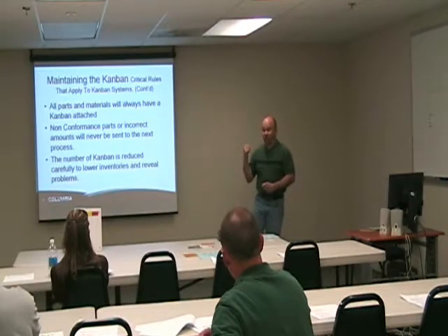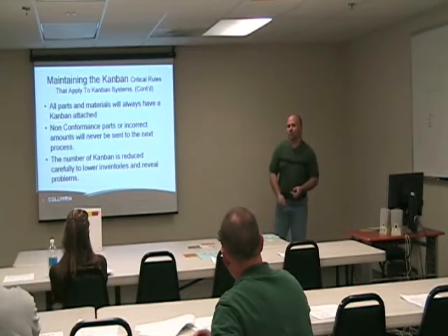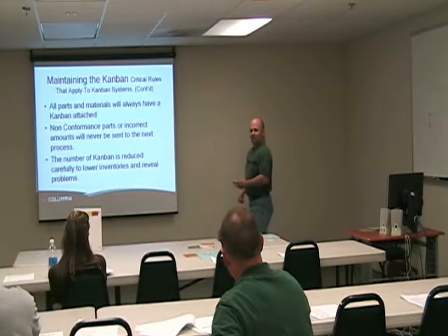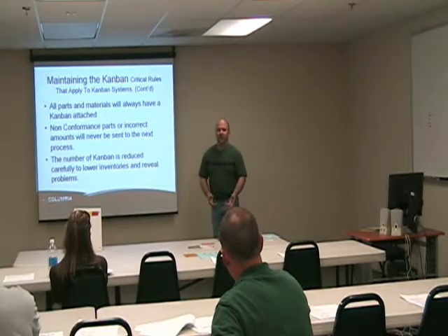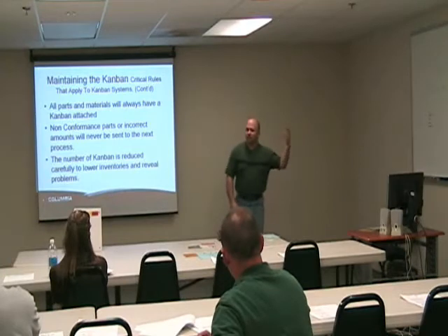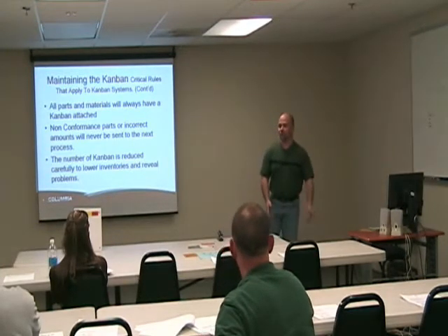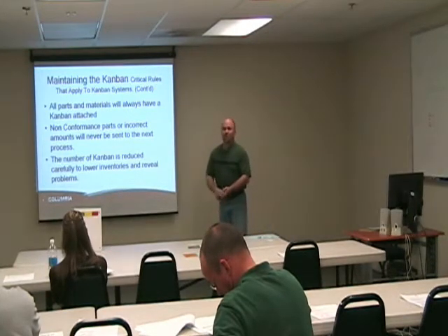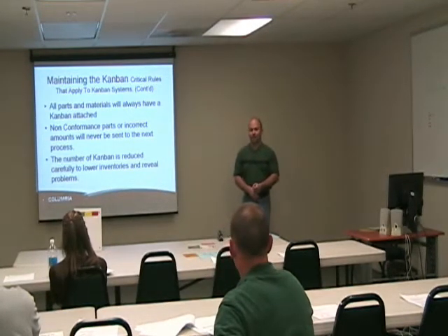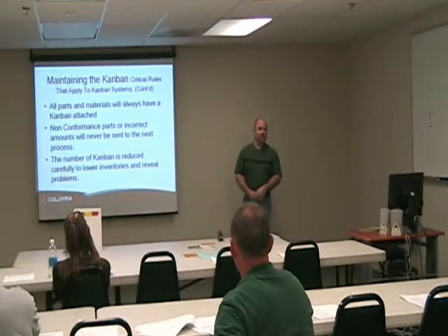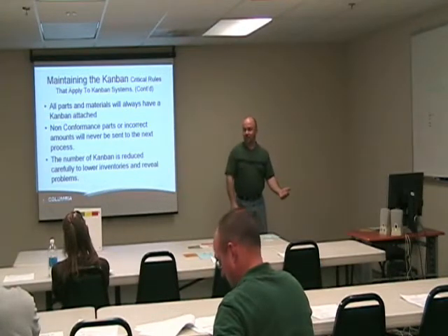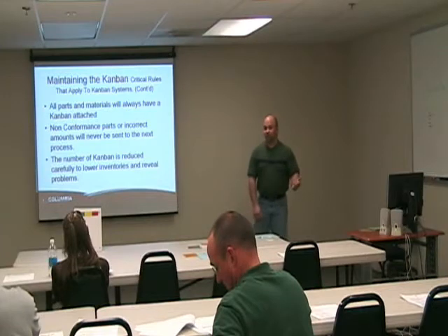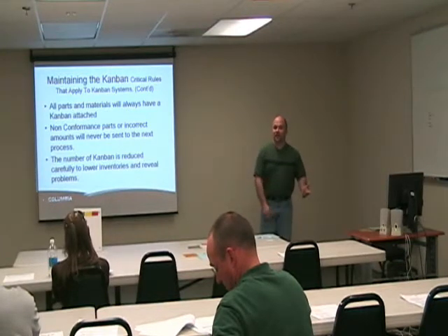So, say our baffling that I showed in here earlier. What if we had a buffer of 10? But every third part that we get from our supplier fails. It's NCR and gets scrapped. Well, we have a buffer of 10, big deal, so what? That doesn't hurt us any. We can absorb that and keep working without feeling it. So now is the best time to drop that buffer down to 5. Now we're going to feel that third one a little more every time. Now we can get a team in there to find out why this part is failing, why we have such a consistent loss, and we can get this fixed.